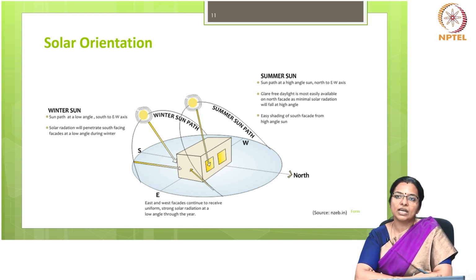In winter, when the sun is lower in the sky, buildings should be designed to maximize solar heat gain. This can be achieved by having larger windows on the southern side to allow more sunlight to enter and warm up the interior spaces. Additionally, using thermal mass material on the southern side can help store and release heat, contributing to better thermal comfort and reduced heating needs.